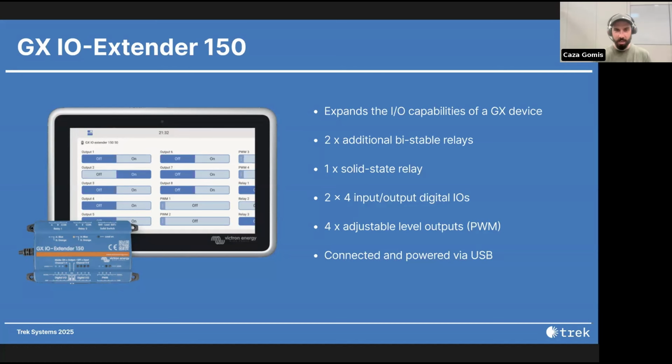Which, someone mentioned in the chat, yeah, with a 2-wire, you don't need additional components. With a 3-wire, if you have this Elevation, which basically takes the 2-wire signal and converts it into 3-wire for the Onan, now you also have the advantage of all of the built-in settings from the Cerbo or the GX device interface that allows you to do things like quiet hours and starting based on certain conditions like state of charge, that kind of thing. So using the native GX relays is still probably the best bet when it comes to generator auto start stop.